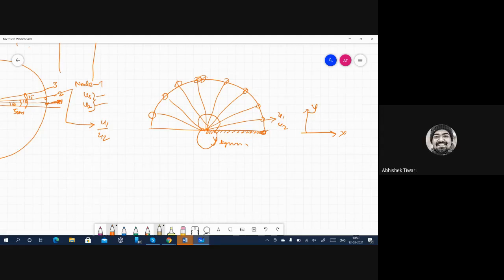Yeah. So Monday you should try. Monday there will be this thing which we will be doing, so you must try making this. It is very simple. We have to model it in 2D. Everything remains the same: 2D, deformable, material property, making section, assigning section to the material. That part is done. Go to the assembly module, import it as an assembly. Then go to the interaction module, do nothing there.